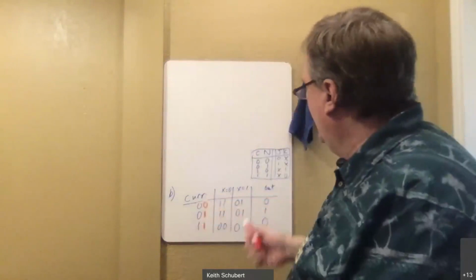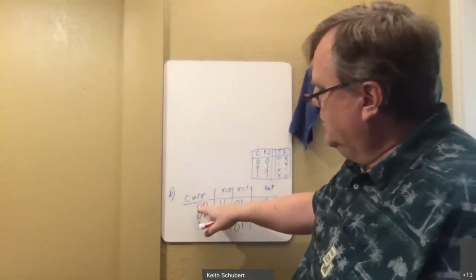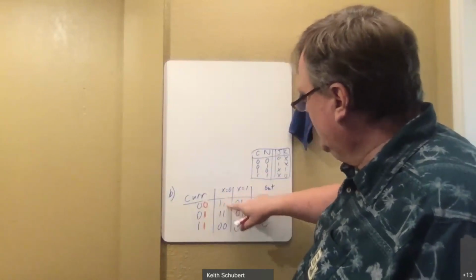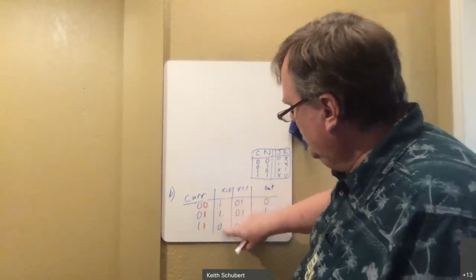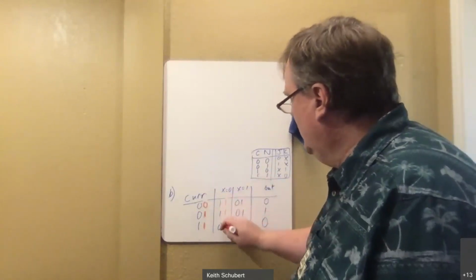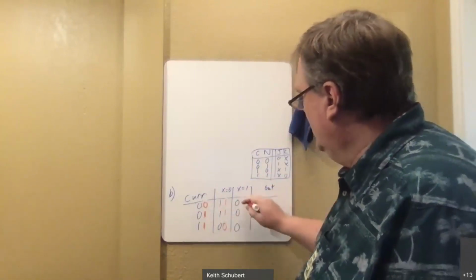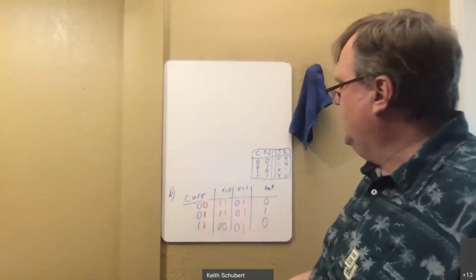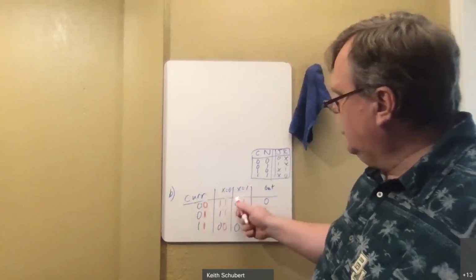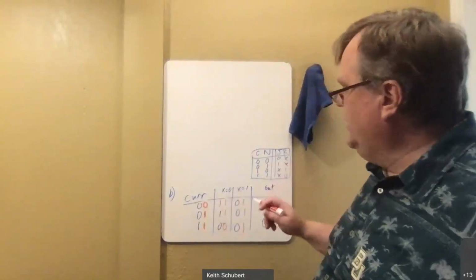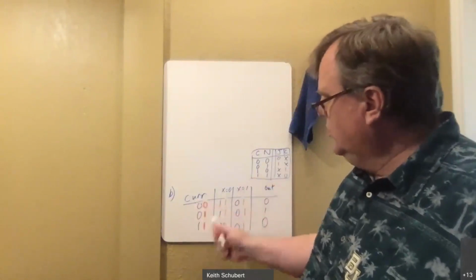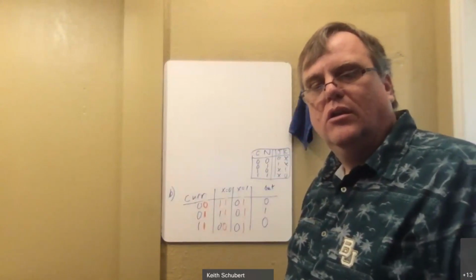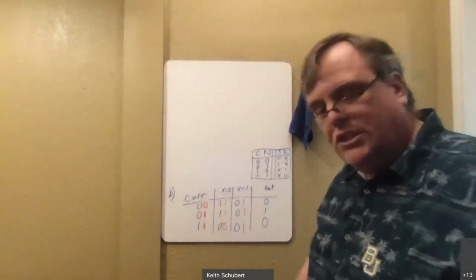You just need to separate the two out because I'm basically going to have the left bit changing from a 0 to a 1. So I'm just doing most and least. And so the pattern on the right here is 1, 1, 0. And here it's all ones. Right. So the blue bit transitions to the blue bits, the red bits transition to the red bits. So these are the current states, and these are the next states. So when I'm doing these JK flip-flops, I have to do one for the blues and one for the reds. Is that good? Awesome. I'm going to do the blues, or the most significant bit, first.